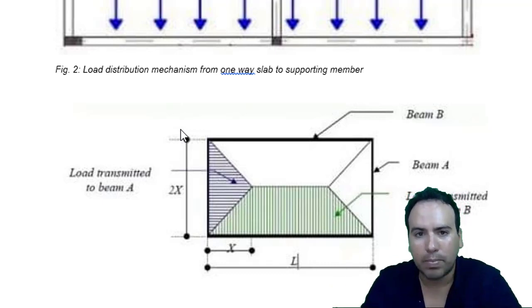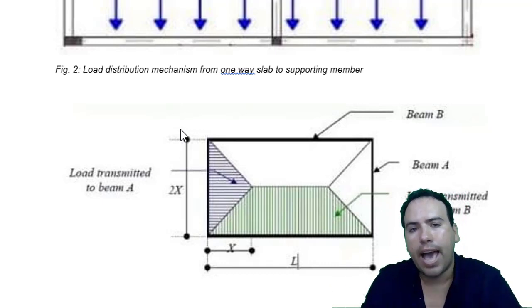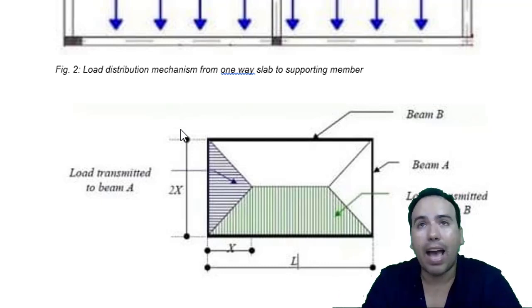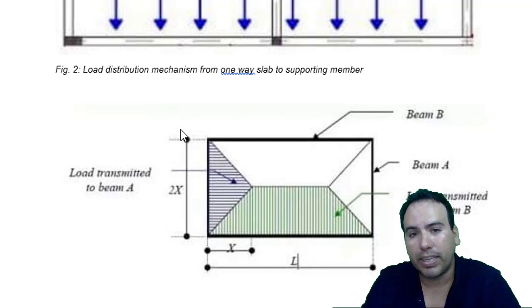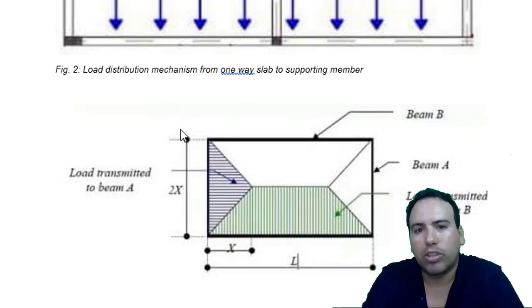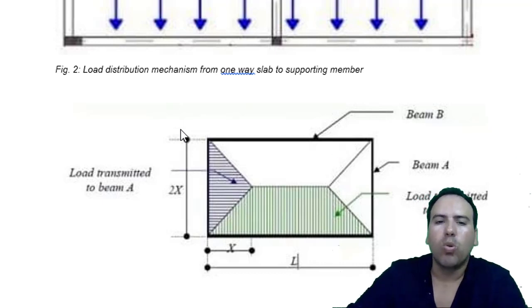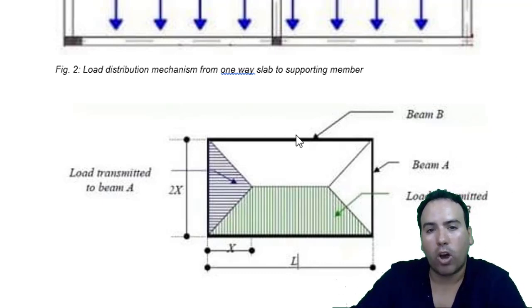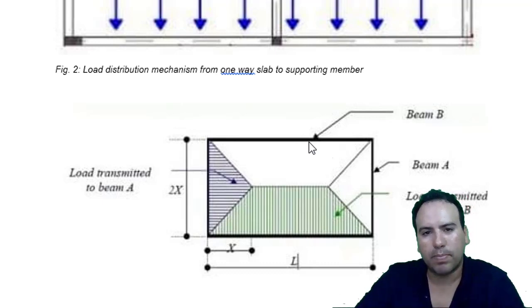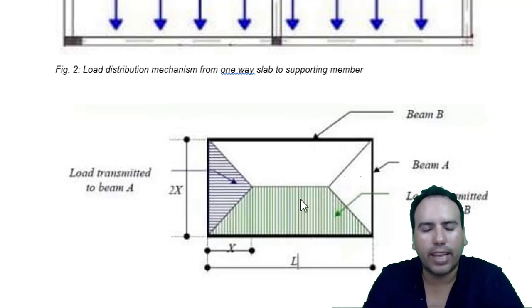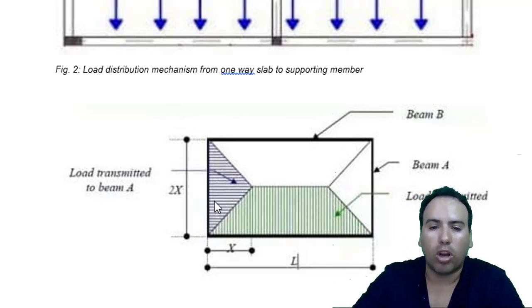That's what I always tell the people who ask me, saying I have a slab and it is 25 square meters. Given the square meters, the number of square meters is not as important. How much your slab is, say 4 meters by 13 meters, is more important than the number of square meters you have. So we can pretty much watch the spans. The longest span and also the shortest span are the most important things to watch out for in the calculation of the slab and the structure.